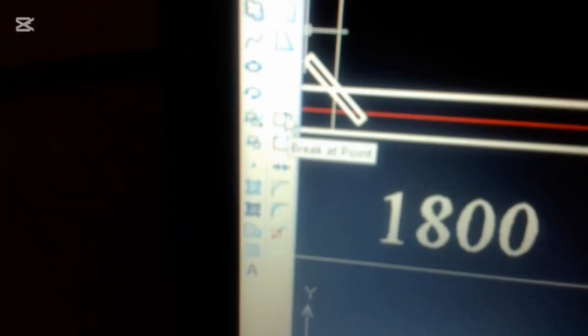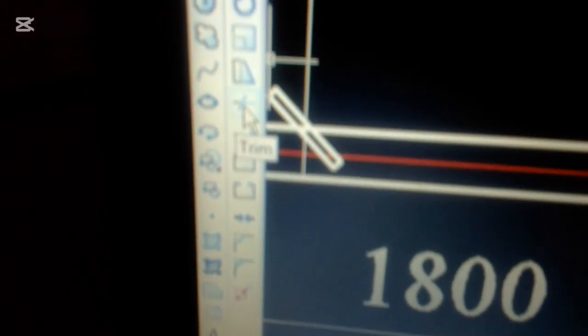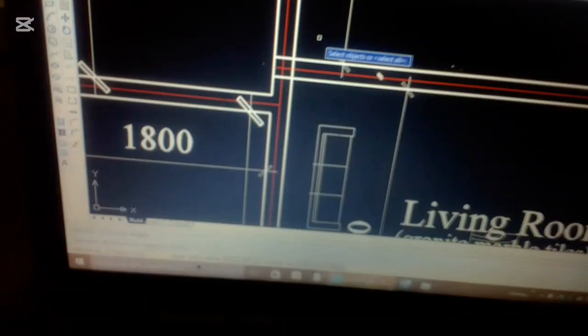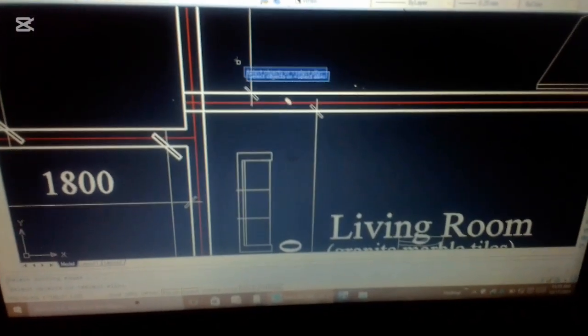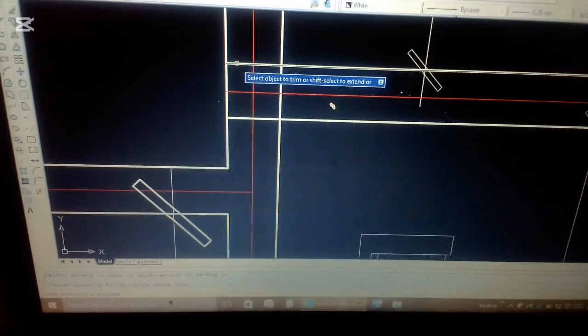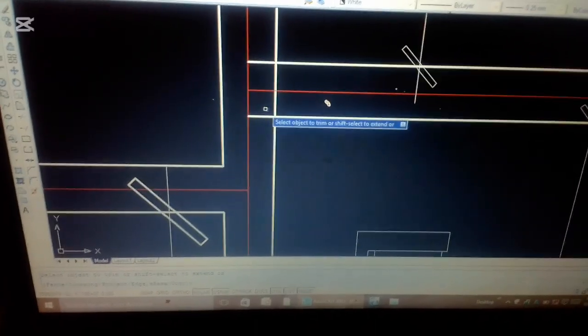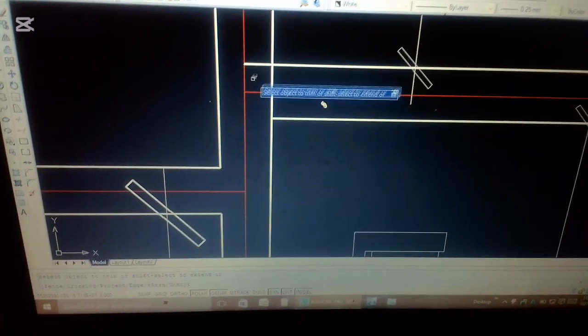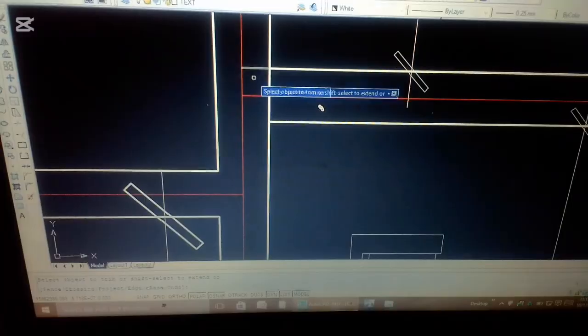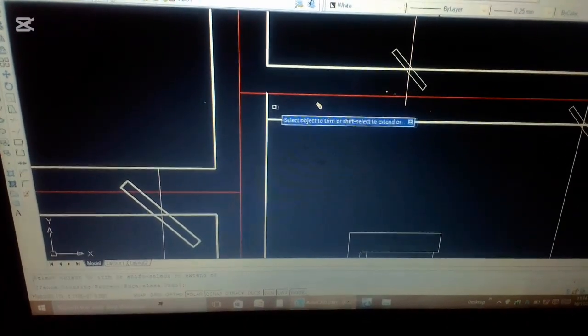I'll have to go ahead and click on my trim command on the tools icon. So I'll click on it, and the next step is to left click, the same method I've used in extending. So I'll left click on an empty space, not on any drawing, then right click to trim. That's what I'm doing. I'm just trimming, I've already done it.